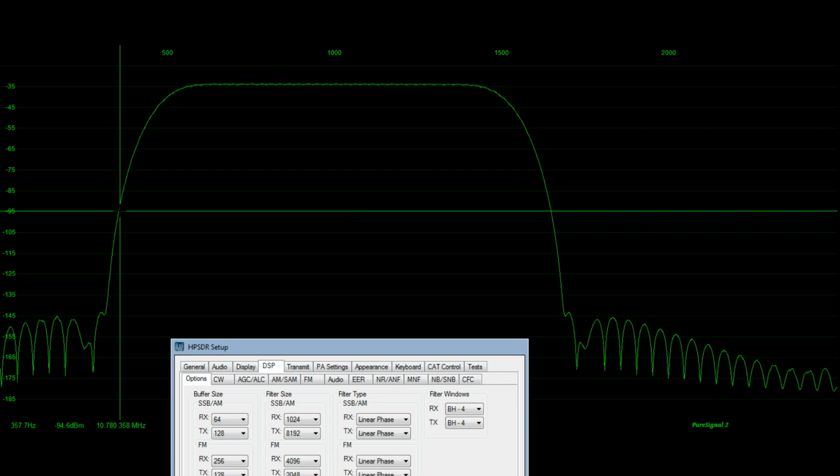So we're now at 644 hertz, which is our minus 60 dB value. We'll divide that into our minus 6 dB value, which is 500. And when we do the calculation, the shape factor comes out to 1.28. And that's the basics of calculating the overall shape factor of any filter: to reference what the bandwidth is at minus 6 and minus 60. In this case, there was just some extra calculation and understanding of how the actual numbers relate in the software and the spectrum view to understand actual bandwidth.